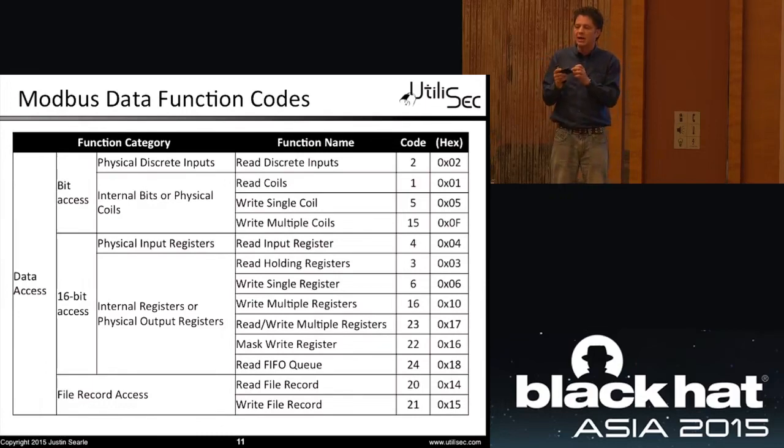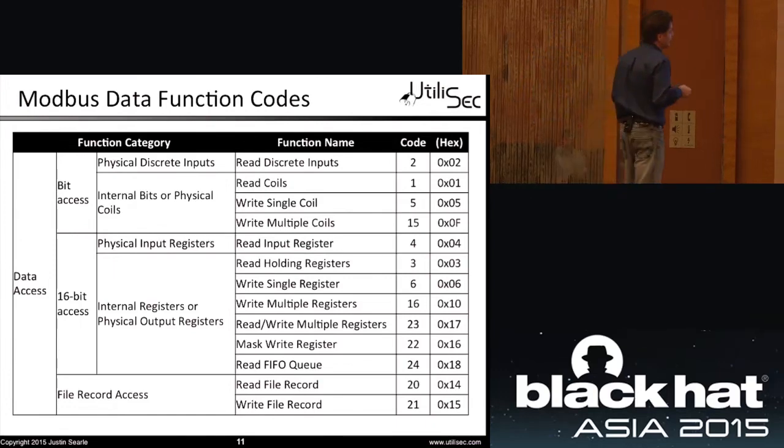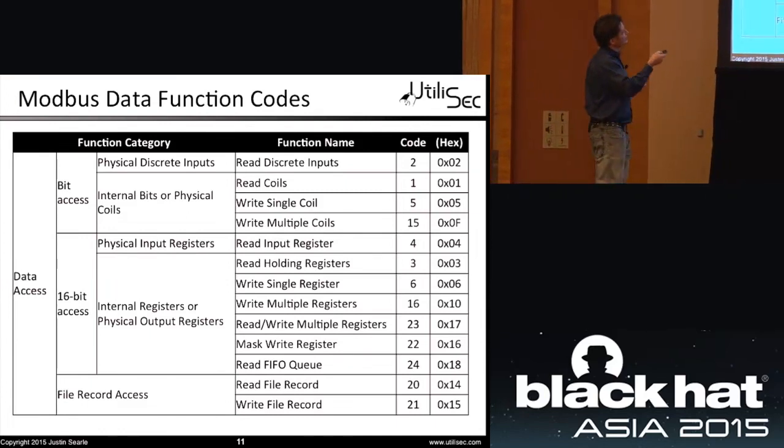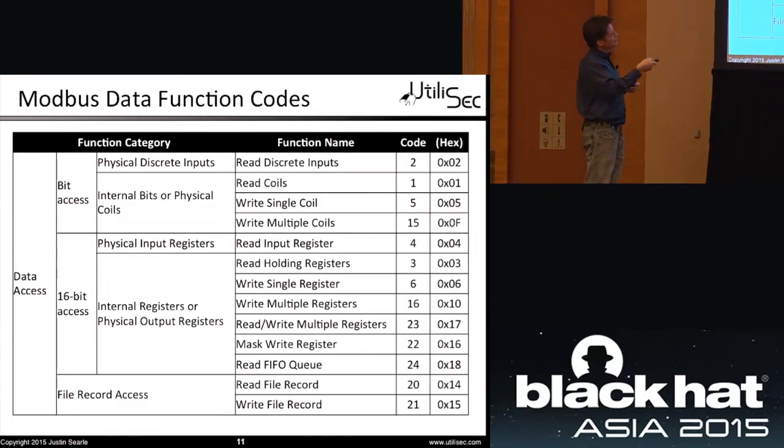So if I have an analog output, say it's going to be something like setting a temperature for a thermostat or setting a temperature for some type of a vat that we're boiling. We can set a temperature, and the PLC will automatically know based on whatever temperature we set. So we set it to 150 degrees Celsius. The program inside of here will know that 150 degrees Celsius is equal to this 16-bit number to be able to send it on to whatever product that we're working on. So that's bit level access and byte level access for the analog.